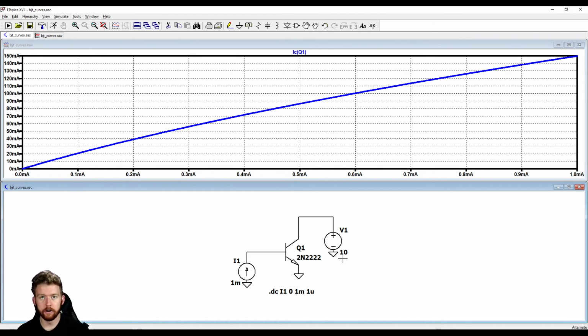So what I encourage you to do is play around with this simulation, make it for yourself, and maybe see how changing this voltage or changing that collector voltage impacts this current. Is our current always the same no matter what base voltage or collector voltage we have, or does it maybe change at one extremity or the other? I encourage you to do that to really get a feel for these different operation regions where we want our transistor to be operating, okay?